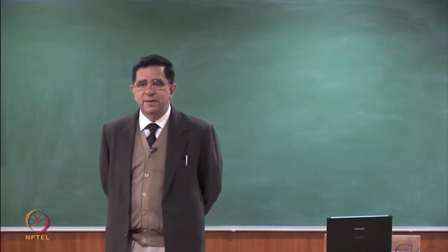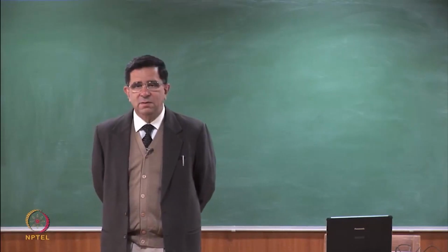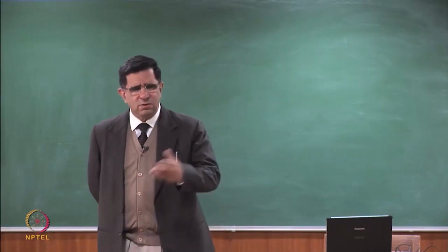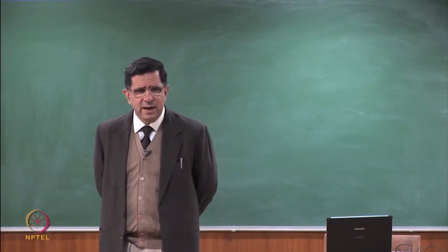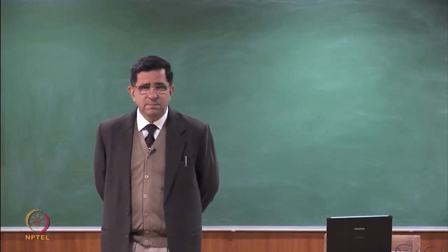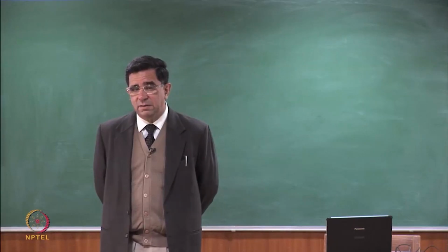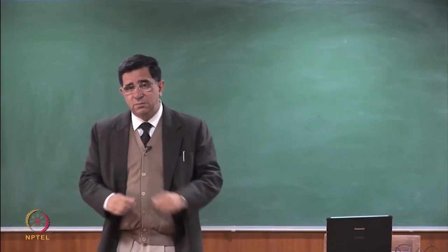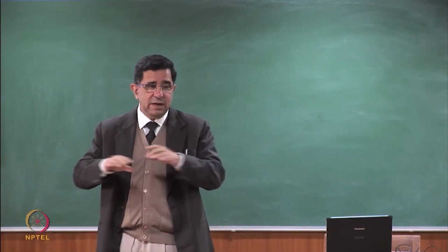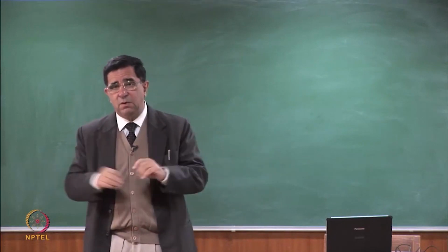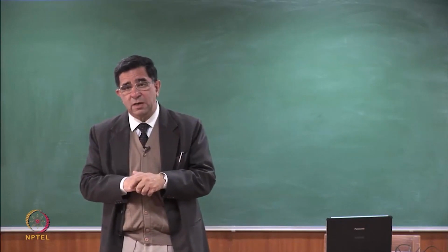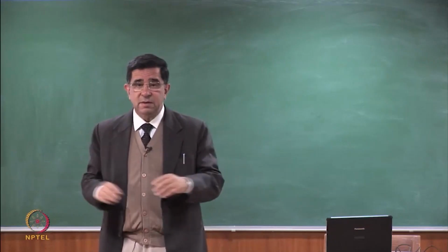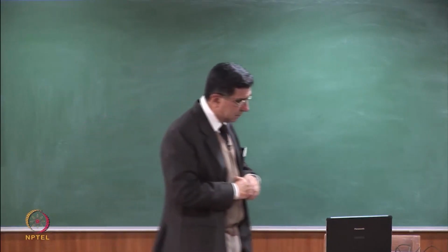So good day to all of you, and welcome back to our lectures on stability of slopes of landfills, which I think we are continuing from the last one or two lectures we have already had. These are critical issues for landfill design, because I told you that if a landfill is above the ground, the slopes have to be stable, and if we have put some geosynthetics inside the slope, the tendency is for the cover soil to slip off. So we have to be very careful that for 50 to 100 years, this mound that we create remains stable.